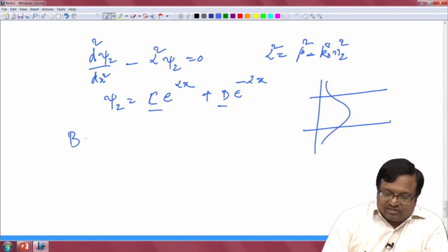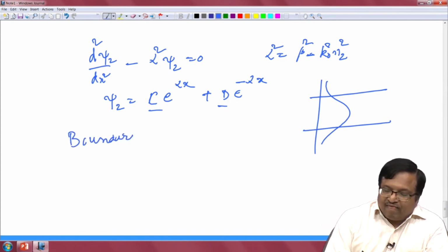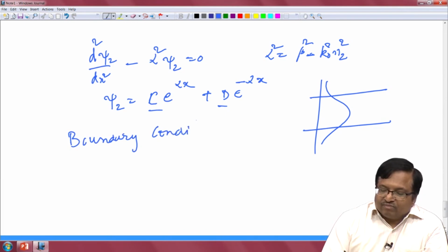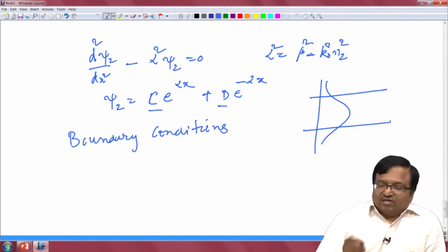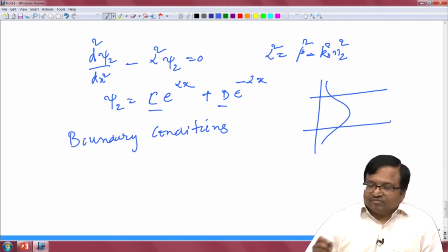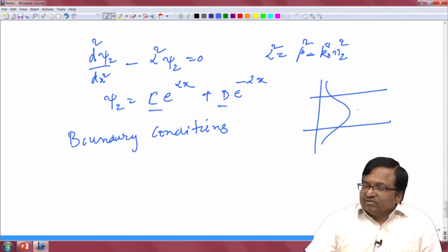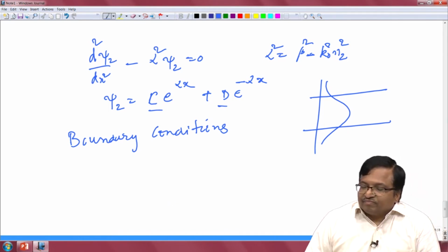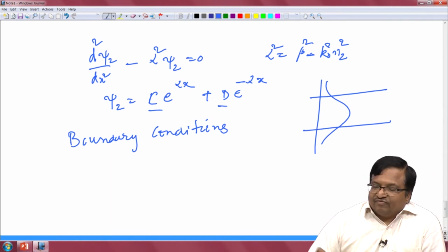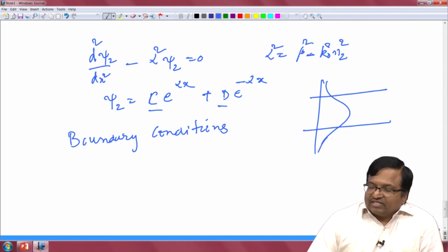So, now we will use the boundary conditions to choose the parameters or the arbitrary constants appearing in the equations. So, we have a field which is trigonometric inside the core region and exponentially decaying or reducing in the cladding region. We can give a rigorous mathematical explanation or meaning for the shape of the fields that we choose, but for understanding purposes let us now choose a very tentative approach and